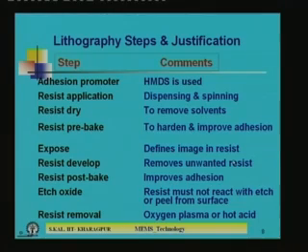As a result, some portion will be developed very fast and some portion will not be developed where the reaction is not completed. So, we need a uniform thickness photoresist film, so that uniformly and equally over the entire surface of the silicon the reaction will be completed, and in the developer solution the structure will be developed at the same time.